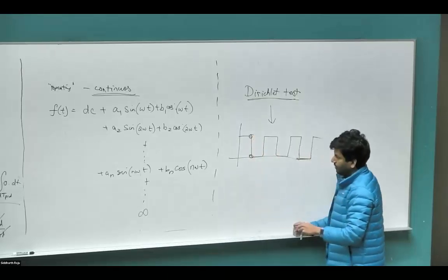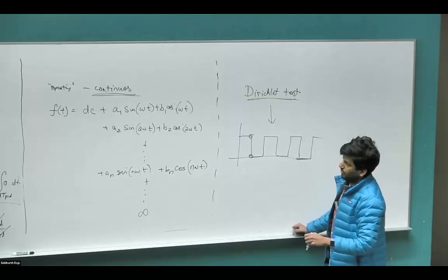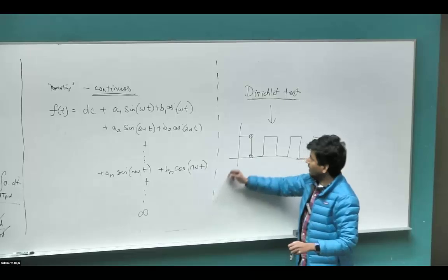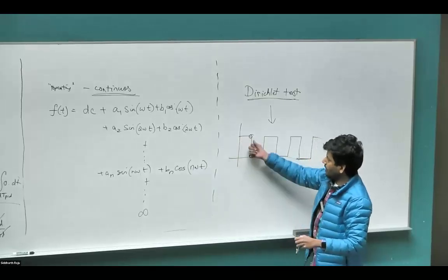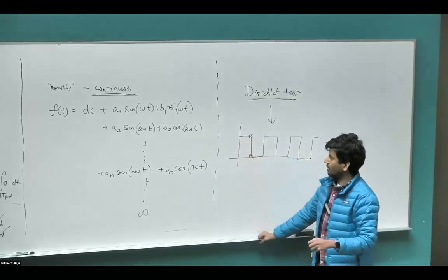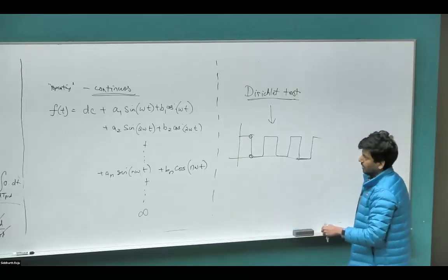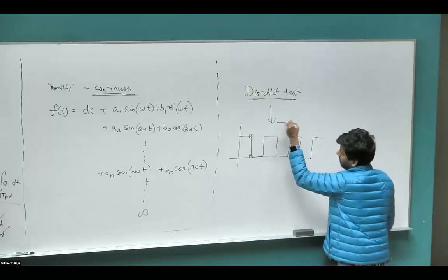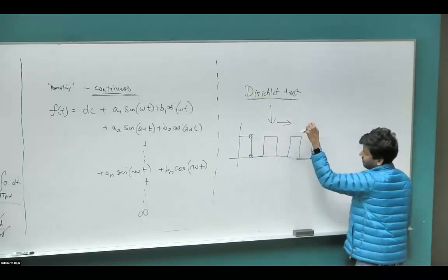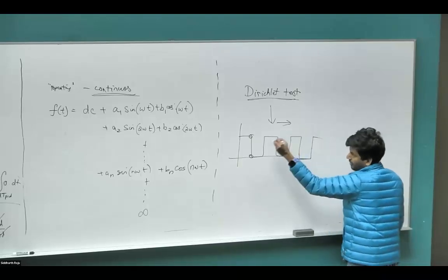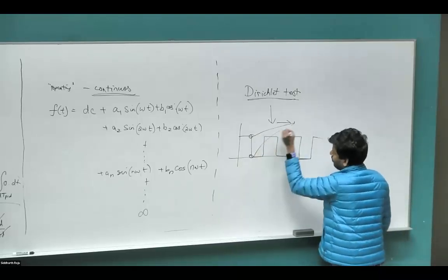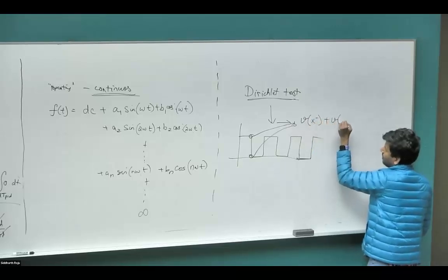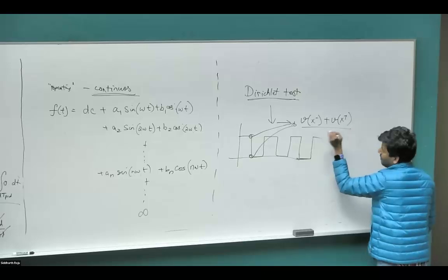So whenever this kind of jump discontinuity exists, the Fourier series does not guarantee convergence. At every other point, if you sum up to infinite signals, you would get exactly the same waveform except at these points where the jump discontinuity, or any form of discontinuity, happens. This is where the Dirichlet test comes into the picture, where he puts down the constraint that if such a discontinuity exists, the Fourier series still converges, but to the average of the two discontinuous values: f of x minus plus f of x plus, divided by 2.